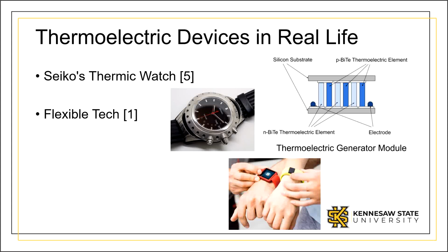To generate power, the watch employs a thermoelectric effect known as the Seebeck effect. This occurs when the ends of two different metals are exposed to two different temperatures, creating a potential difference. To harness this effect, Seiko created a module composed of 104 or 52 pairs of semiconductors utilizing P-type and N-type elements. To produce the semiconductor elements, a bismuth and tellurium-based material was used.